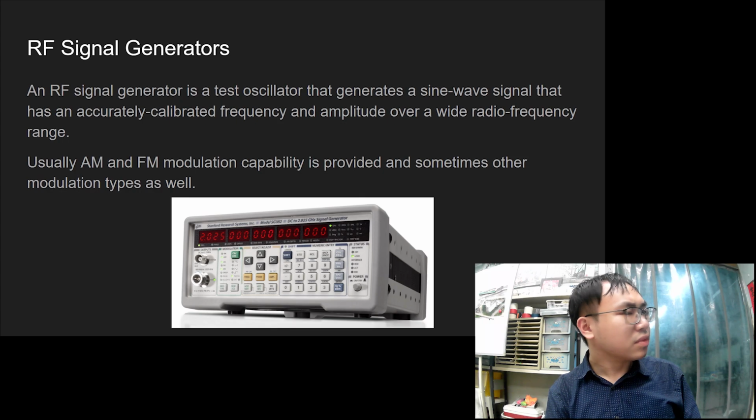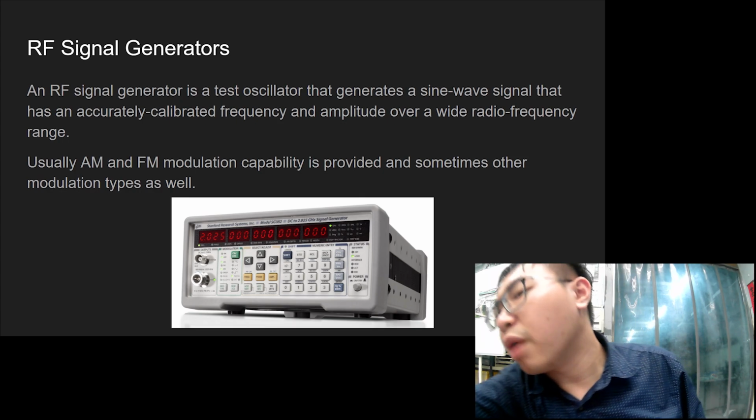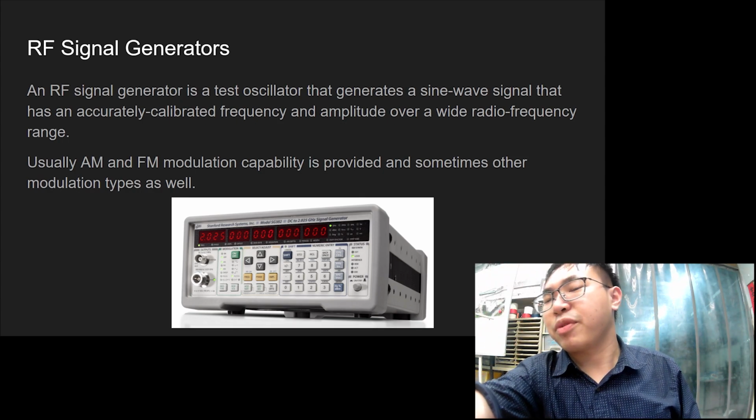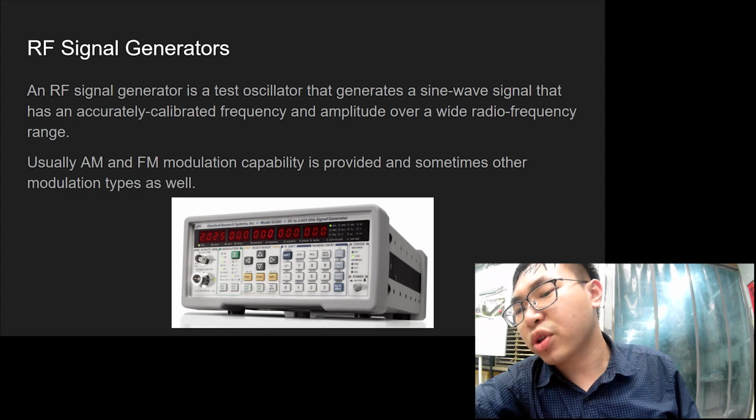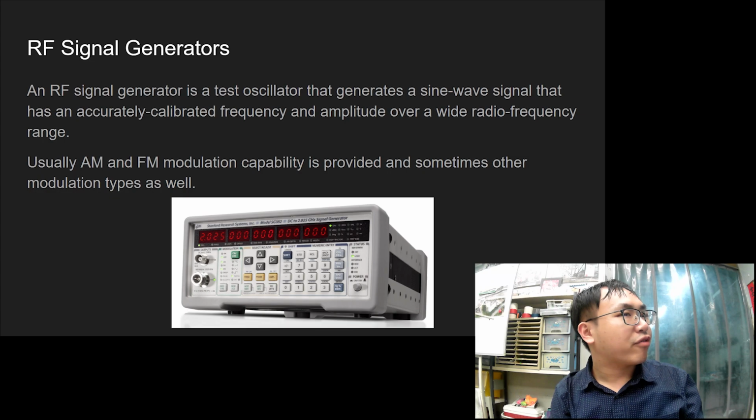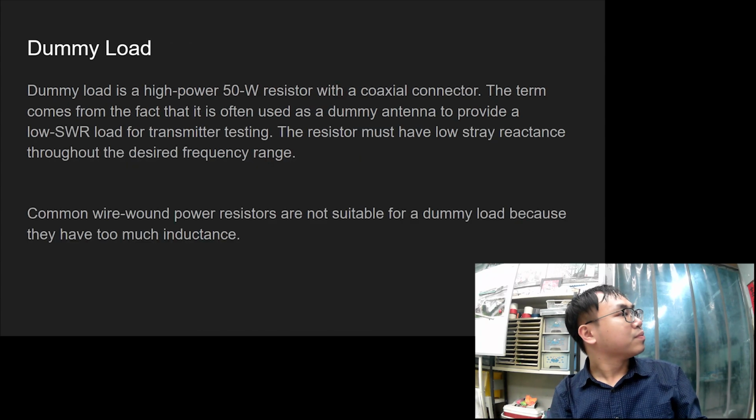Okay. So as I just mentioned, this one you have to calibrate before you use it, right? So also for the oscillator, frequency counter and spectrum analyzer, you have to calibrate them after you use them for some time, like for years. So you have to calibrate it.